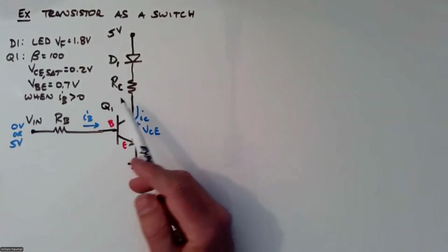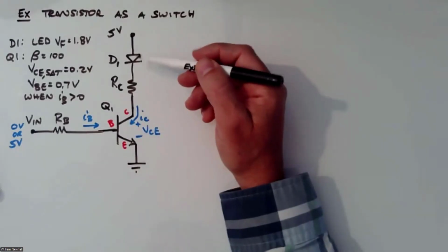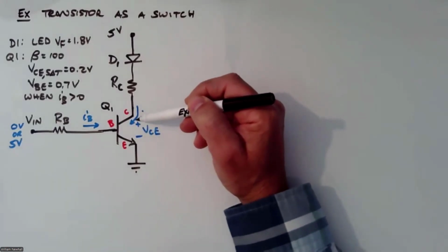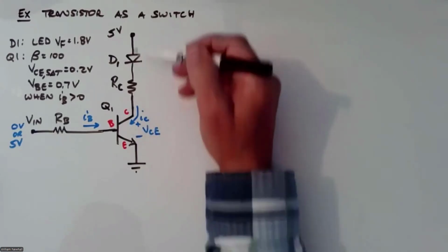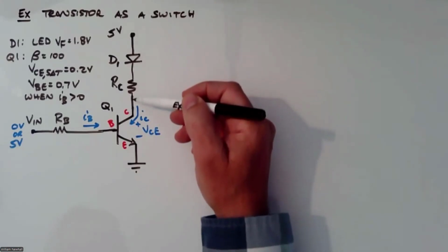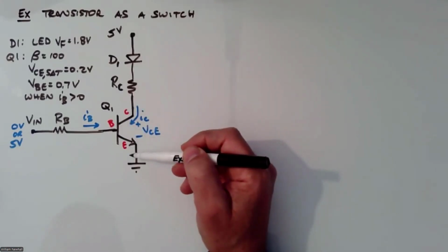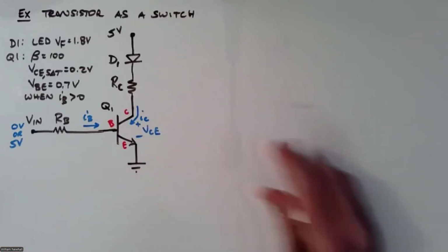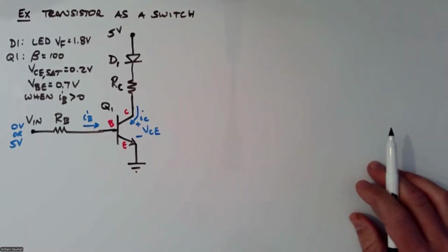So how do we choose these resistor values such that when this transistor is saturated, remember, saturated is like a closed switch for a transistor, what resistor do we use to get 25 milliamps, let's say, flowing through that diode? And then what base current do we need? Or alternatively, what resistor value do we need here when you apply 5 volts to be able to saturate that transistor?